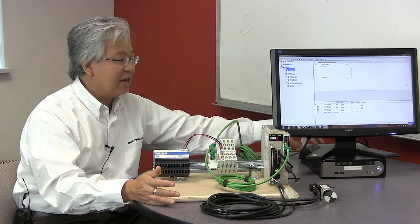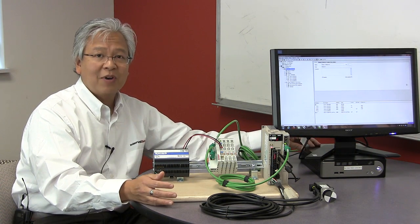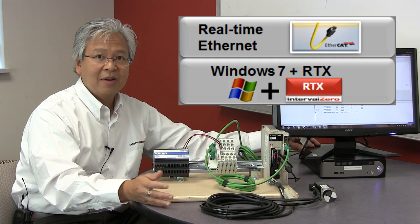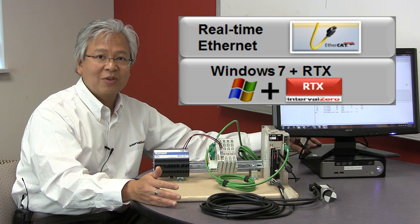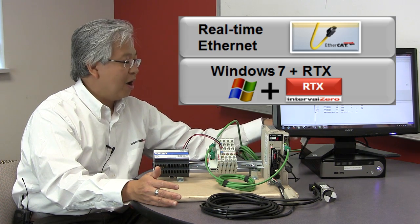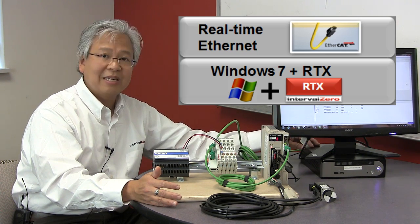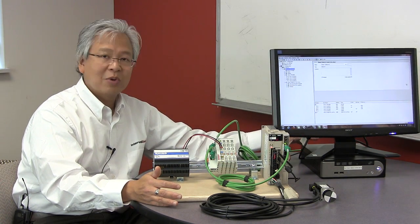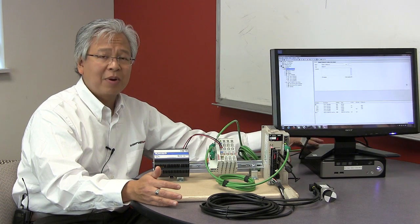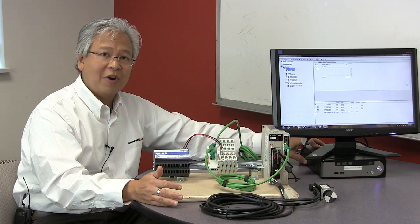Inside of this PC, we have several things loaded. First of all, we have Microsoft Windows 7. On top of that, we have RTX, and RTX transforms Windows into a real-time operating system. On top of that as well, we have the EtherCAT software. There's the actual SDK, and there's something called the EtherCAT configurator, which we'll talk about later. So all of that is what's loaded on the PC. Again, there's no proprietary hardware inside of here. It's all using standard commercial off-the-shelf hardware.